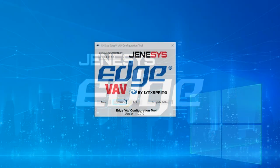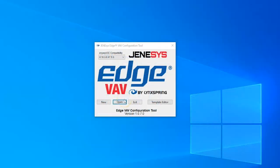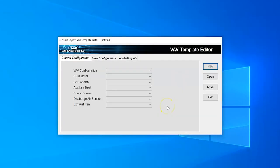The template editor window is accessed only from the Start display. Its layout mimics the control configuration, flow configuration, and input-outputs tabs on the VAV entry window. Users can use a template editor to build VAV configurations specific to a particular region, box, manufacturer, size, and input and output configurations. There are 4 buttons used for the file template management.